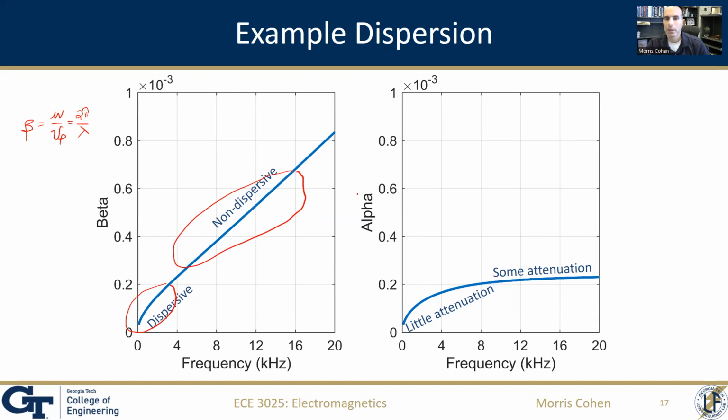On the right is this attenuation, or alpha, in units of nepers per meter. So this is how many 1/e reductions are we seeing every meter. And that starts out with a value that technically at DC it's 0, and then it slowly increases in this sort of fashion. At 20 kilohertz, it had reached a point where the 10 kilowatt signal drops to 6.3 kilowatts, but you can see the trend is clearly increasing with frequency. And as the frequency goes up, it will increase even further.